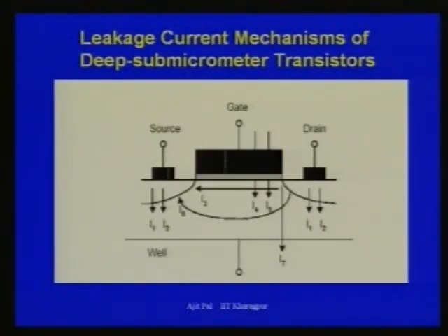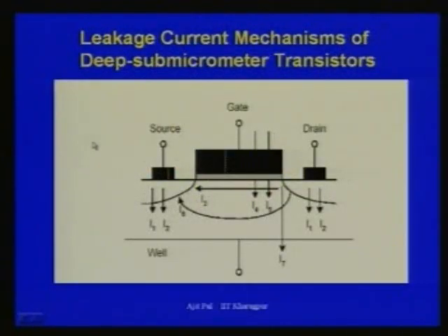Then coming to the leakage power dissipation, that standby power, that static power is essentially known as leakage power. That means when the circuit is in standby mode, the inputs are not changing, clocks are not changing, but the circuit is connected to the supply voltage, and as a result it will lead to some power dissipation, and it is primarily due to leakage current.